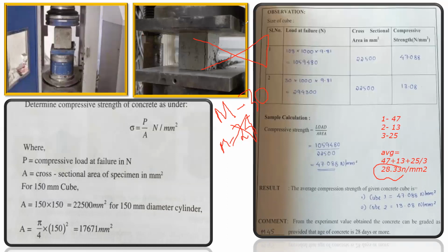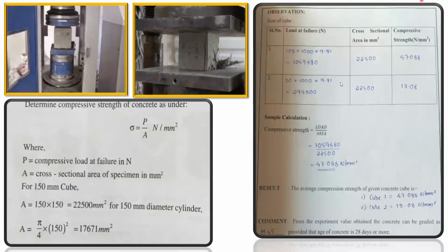Yeah. Right. So this was the entire procedure of the compressive strength test on the concrete. And one more point, whenever you apply the load on this, the final value should not deviate by 10 or 15% of the mean value. That means, because these are practical things, simply doing the cube testing will not help us. We need to understand the fundamentals of this.